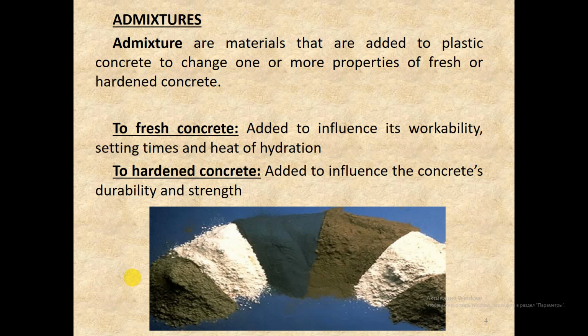Hence, concrete with this admixture both hardens and gains strength quicker than untreated mixes. The concrete remains workable when first mixed and achieves similar 28-day strength to untreated concrete.